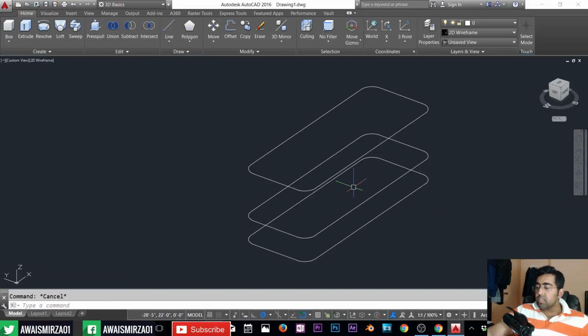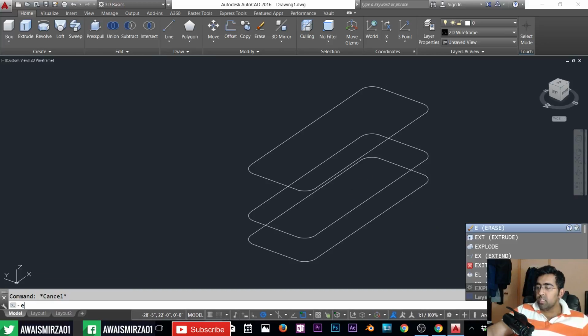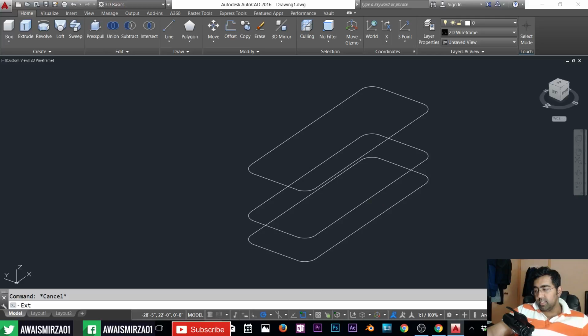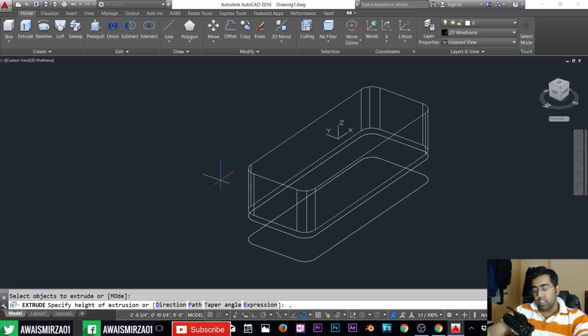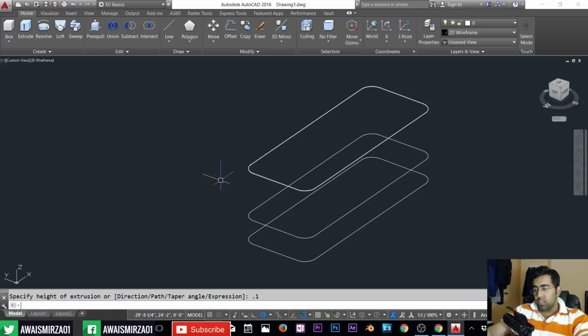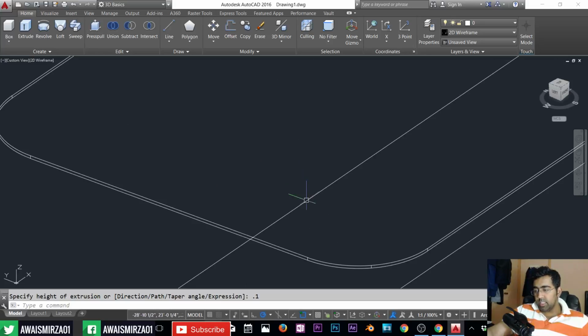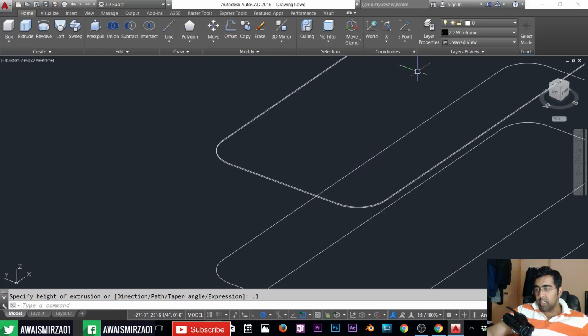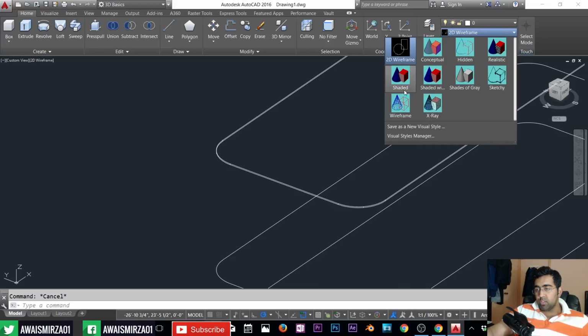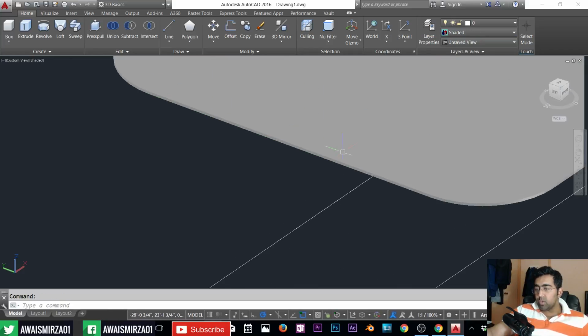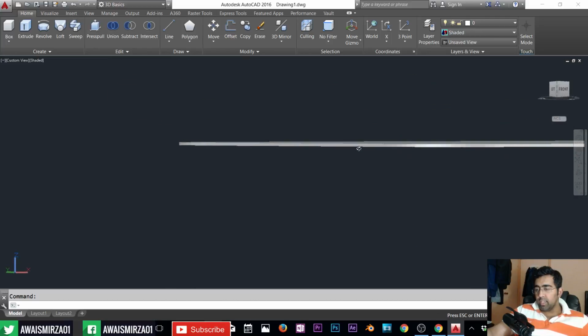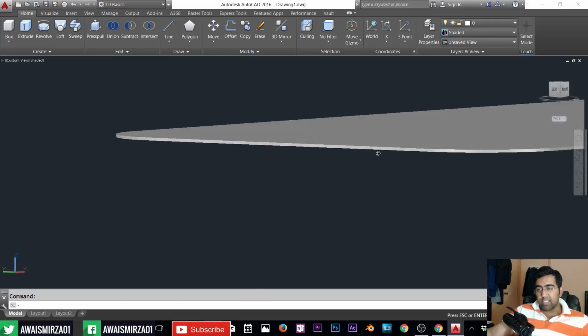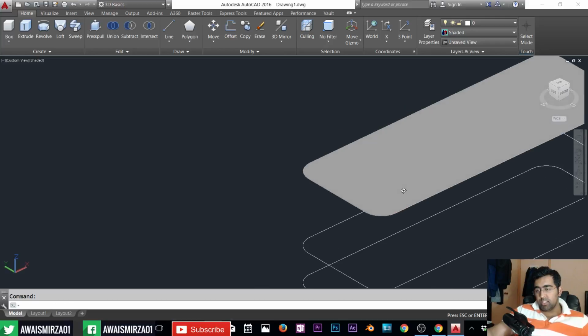Now very simple, just extrude this. ext is an extrude command, and done. I'm going to type 0.1". Okay, so let's see how it is. I'm going to change the viewport to 3D shaded, and we could see how it is. Okay, that's glass actually, so that's done.